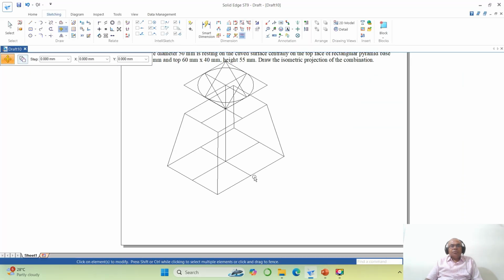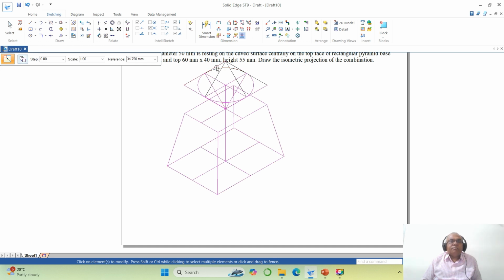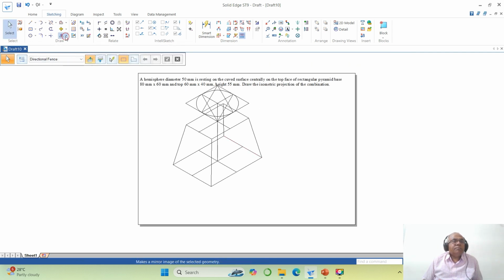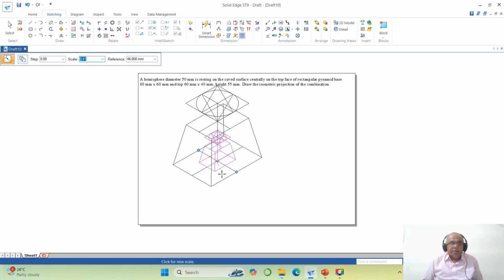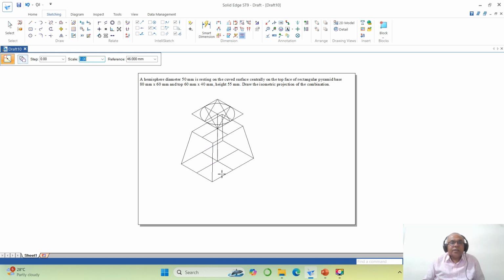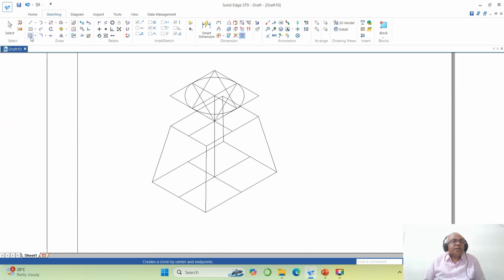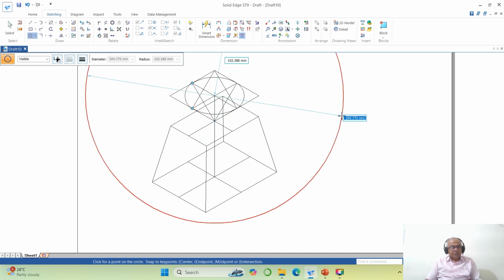So to do that, I will go for a scale, select this entire drawing, sorry, go to fit, then you go to scale, select this entire drawing, take this end point, make it 0.816, okay, reduce it. Now you go to zoom, select this, go to circle, take end point of this to this, okay, so sorry.